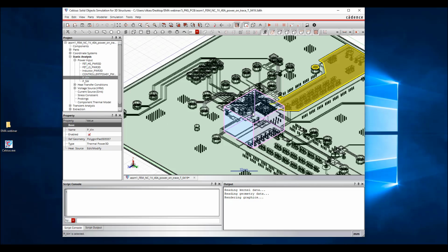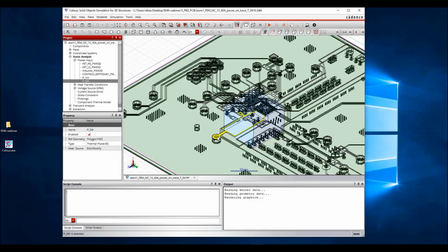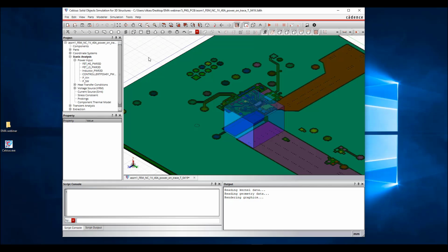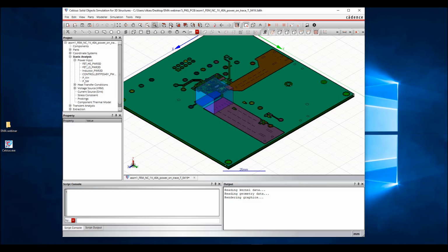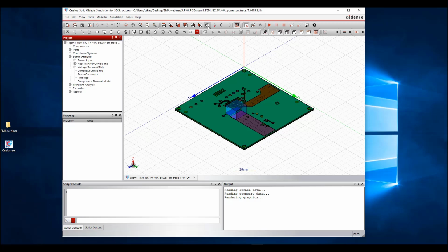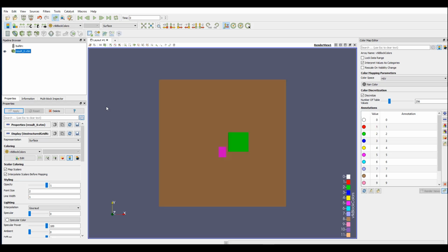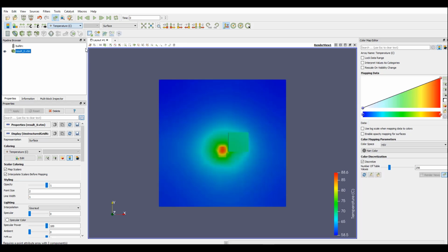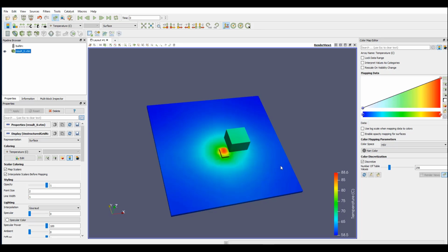For electrical thermal co-simulation, the current can be input into the system through different paths, like we shown here. So it depends on the designer and the purpose of this whole assembly. So after we specify boundary conditions and material properties, then we can perform the thermal analysis like before. Let me show you the results to give you a flavor of what this electrical thermal co-simulation can give us. Temperature, let's run temperature like before. Yeah, this will be the results.